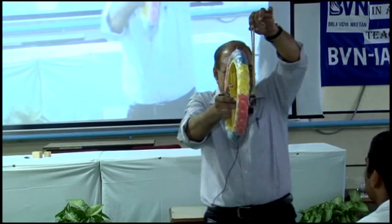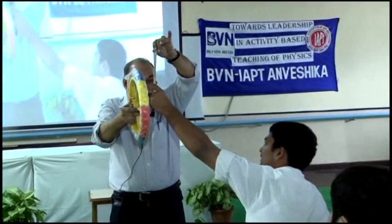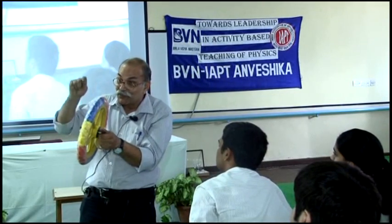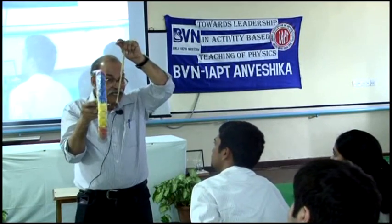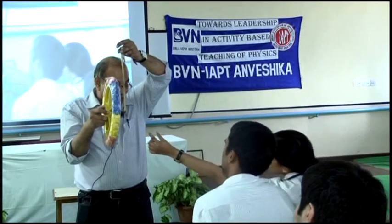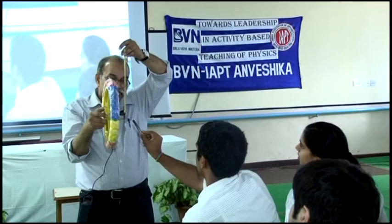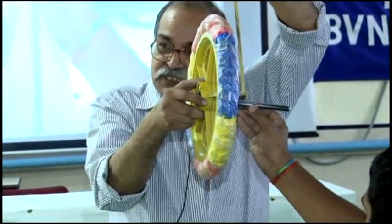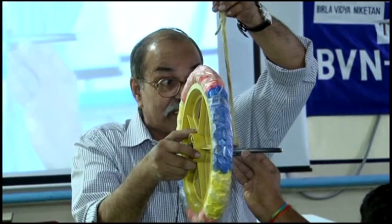Tell me where the force is applied. Put the finger where it is applied. So it's applied upwards from there. My system is this wheel, so that external force has to be on some point of this wheel. It's applied on this point, correct? So where is the position vector r? Put your pen in the direction of r. So now you can see the position vector r, and the force which is upward. Tell me, what is the direction of r cross F?